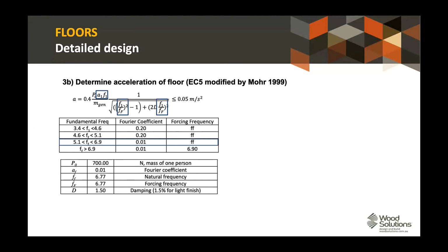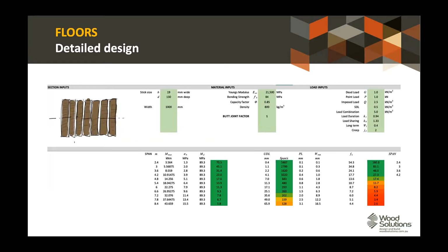And so if you're working with a developer that says, well, this floor's not quite as I expected, find out what the detailing is, find out what the kind of floor structure is. Is it a solid diaphragm? Does it have aerated concrete blocks, for example, that just sit on the joist? How much blocking is there? What are the floor finishes? What's the ceiling? And then capture the data as someone's walking around. If the developer says this isn't what I expected, find out what the frequency response actually is, what the damping is, and start to chart it back to some of these acceptance criteria, because we can certainly do a lot as an industry to start to build this kind of body of information.